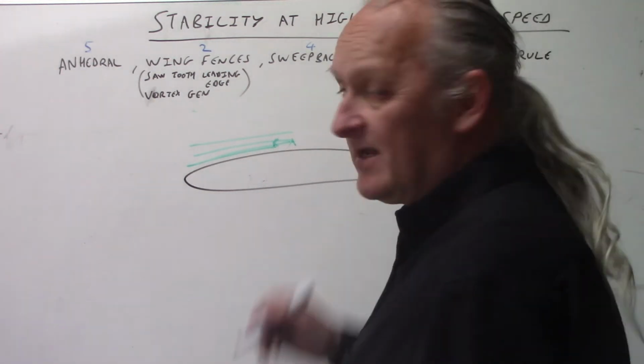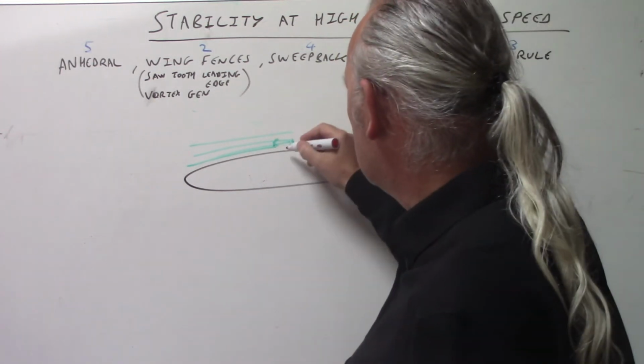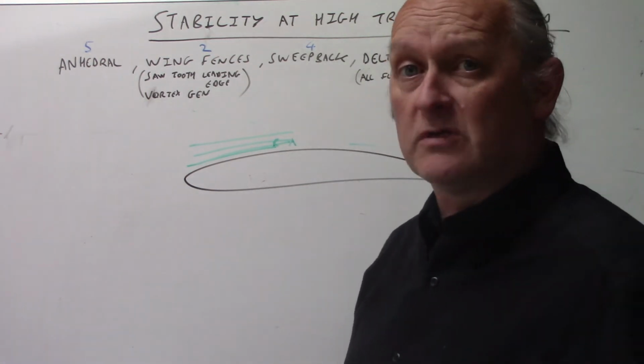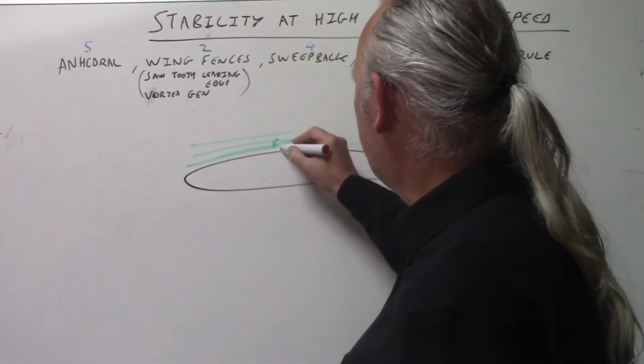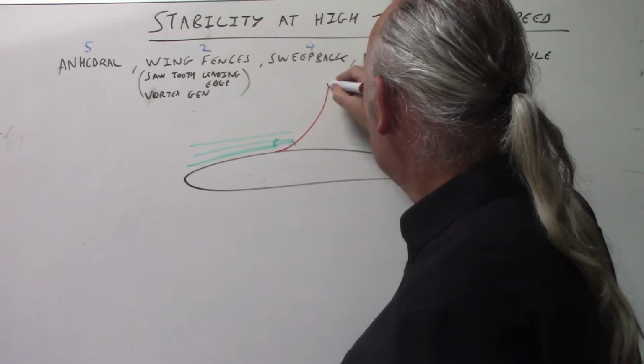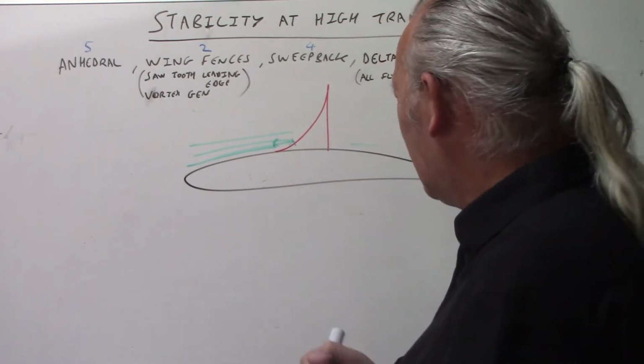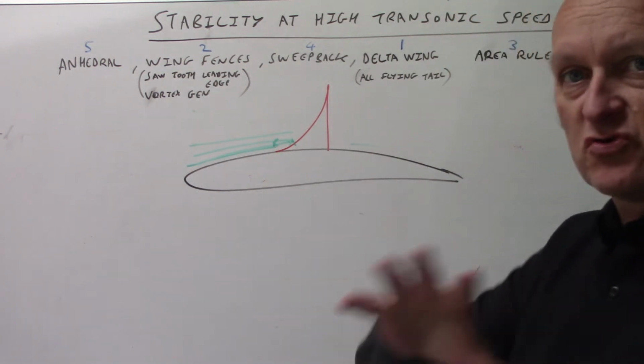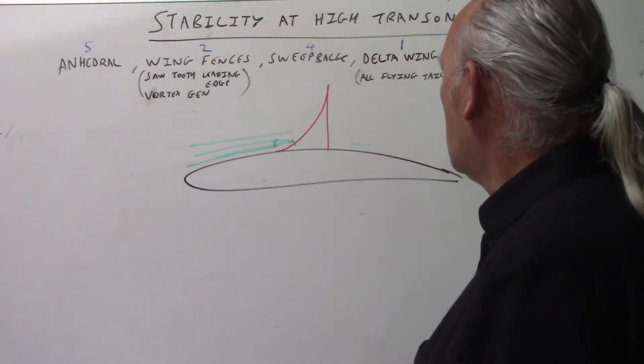Now, again, this is the very basic Fisher-Price version. Any real aerodynamicists out there will sit there and go, it's much more complicated than that. And yeah, I know it is, but we're trying to make it level 3. So you end up with a shock wave, that sort of shape there, and that's a lot bigger than the shock wave would actually appear on the aerofoil, but that's just so it shows a little bit better. Why is it that shape?